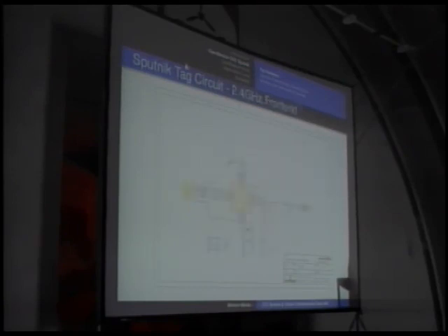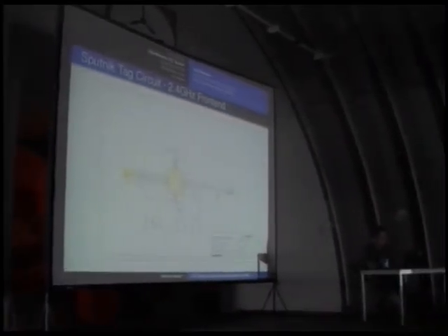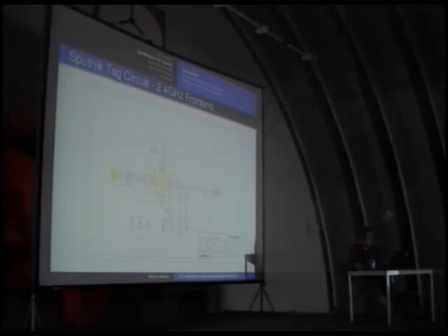And this is the RF front end. So if you do your own schematics, you just have to add this part and connect these I/O lines to two free I/O pins. So that's basically all. And you just take the same values and have a look at our layout. And if you want, you can send us your layout and we will have a look on it if it's done in a proper way, or if you have mistakes, so you don't waste money on PCBs. So if you're interested, just send us your layout and we can check it.